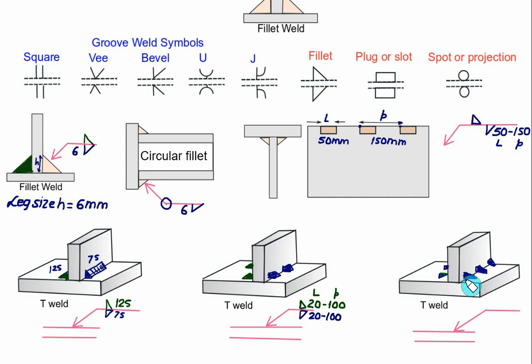Now this one is again a stitch joint but unsymmetric. If it is unsymmetric, then don't show the symbols opposite each other; rather they have to be offset. On the bottom side you have to show the fillet symbol. You have to show the size of the weld, equal to 20, and the pitch is equal to 100. On the other side we have only two pitches, so you have to make it offset and show the fillet symbol, and we have the same weld length equal to 20 and the pitch equal to 100. So this is a little idea about weld specification, what type of symbols to use and how to write down the details about the length and pitch.